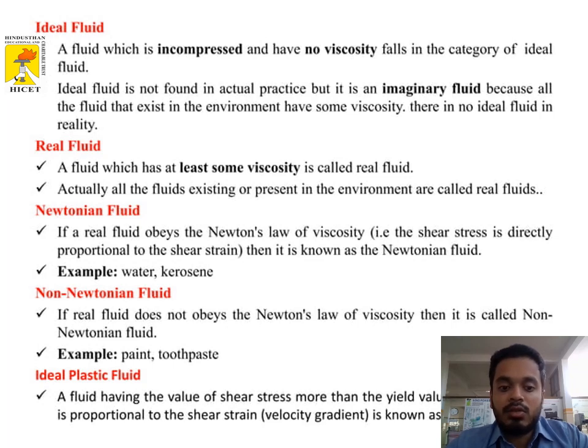Next is Newtonian fluid. If a real fluid obeys Newton's law of viscosity, that is, shear stress is directly proportional to the shear strain, then it is known as a Newtonian fluid. Example, water, kerosene. Non-Newtonian fluid: if the real fluid does not obey Newton's law of viscosity, then it is called a non-Newtonian fluid. Example, paint, toothpaste, etc.